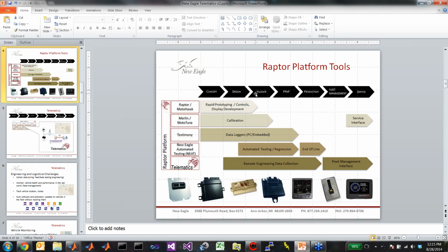The amount of data that can occur on a CAN bus or multiple CAN buses, if you need to collect everything, is a case where you want a physical data logger with a USB stick or an SD card. And so we offer those to assist in the earlier phases, what we were calling the testing line. And with the 320 you can put a 16 gigabyte USB stick in there and collect at a very high frequency.